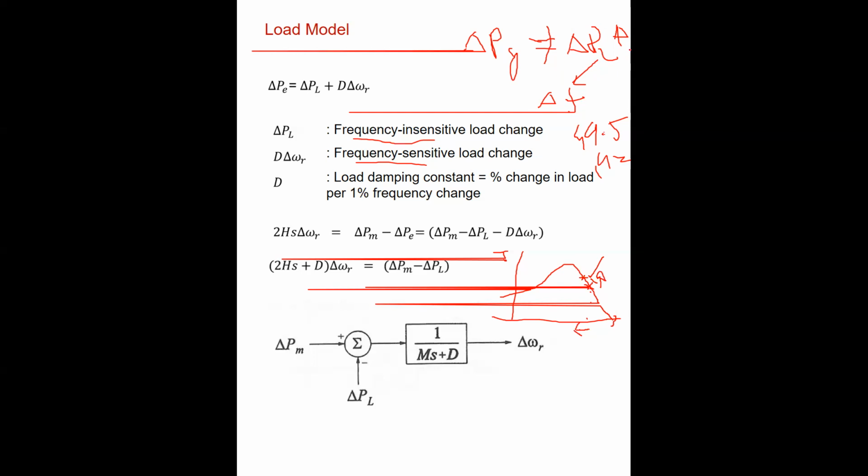Right? Let's say this is your total load, and I said total load is increased. So it is possible that your lighting load has increased, but the motor load is constant. Now, with the load increase, the power drawn by the lighting load, because a lighting load cannot generate or consume, actually it cannot, so the power drawn by the lighting load remains constant even if the frequency has increased or decreased. It is insensitive. Am I right?